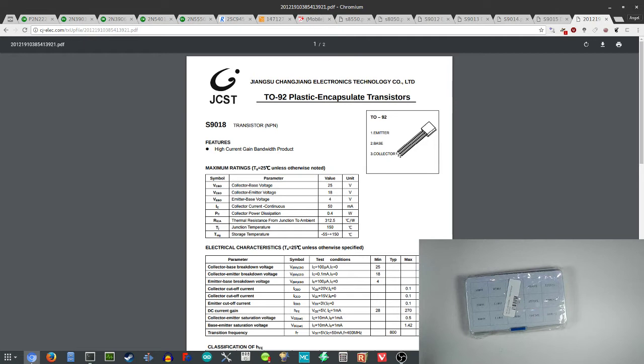There is an option in Marlin firmware where you can have an LED strip controlled by the firmware using G-code. In order to do that, you actually need to use transistors. Here I have a bunch of them that I had laying around that I got for like $5. It's really a lot of them, at least 200 of them.